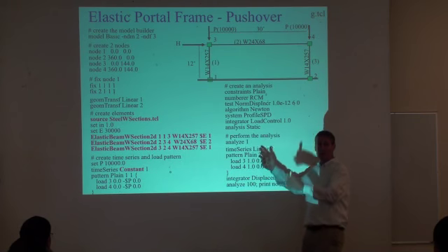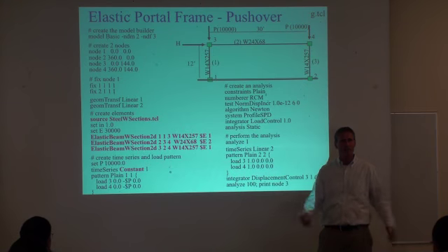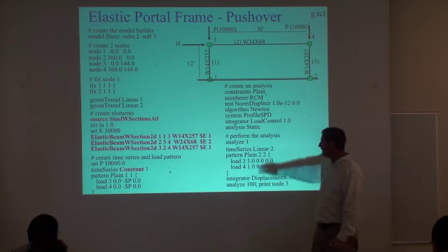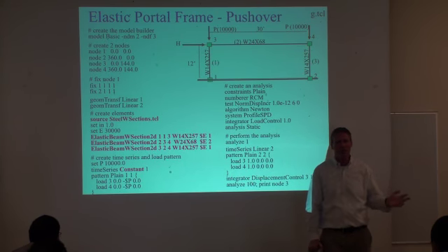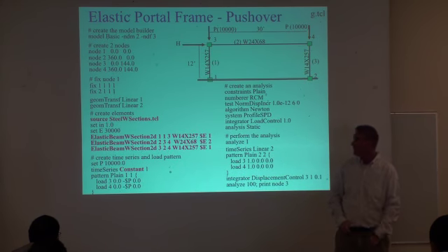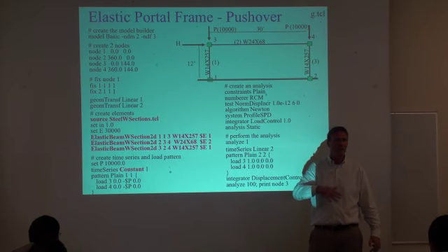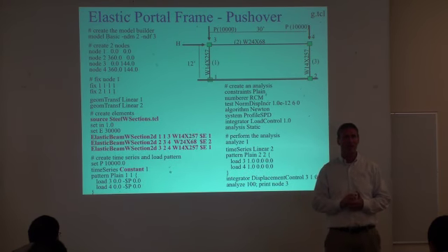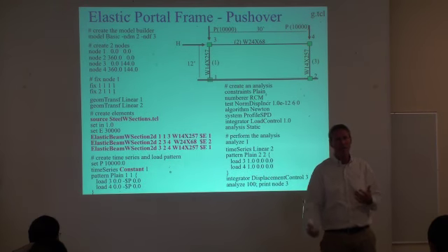And then it says, oh, I've got another load pattern. So it goes through every single load pattern that's active at that time when it hits the analyze. No matter what the time is, you can have as many load patterns in there as you want. You can put load patterns in, remove load patterns, and then add another load pattern. OpenSees doesn't care. We'll get a little into it this afternoon, on resetting the time back to 0 in the domain when you take one load pattern out and add another load pattern.